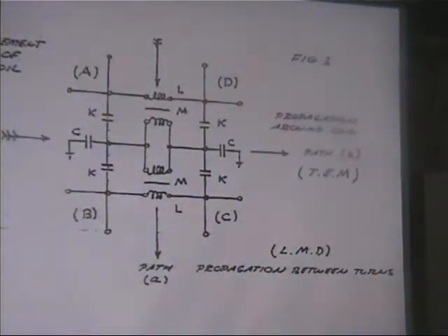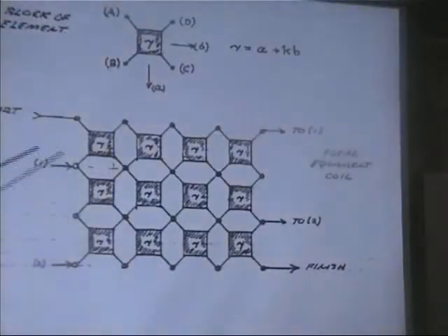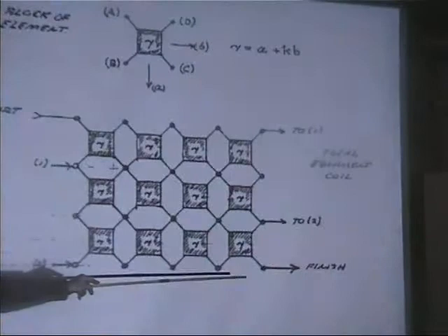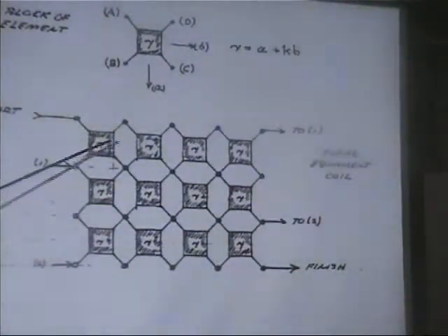Let's keep going. So we take that element and we put them in tandem. This represents a transformer winding, where this is the wire at the phase lead, and this is the wire at the neutral lead. This is how energy flows in the transformer. It is a very complex relationship, and now it's not just a simple A plus jB. Now we have what are called 2 degrees of freedom of propagation instead of 1, and that gives us a 4th order differential equation, which normally can't be described in a spatial reality.